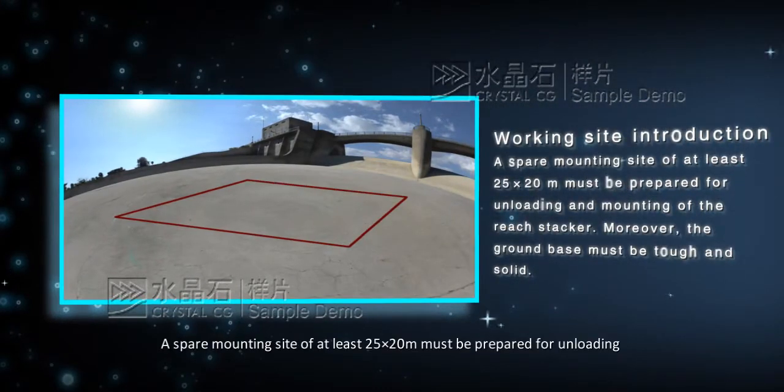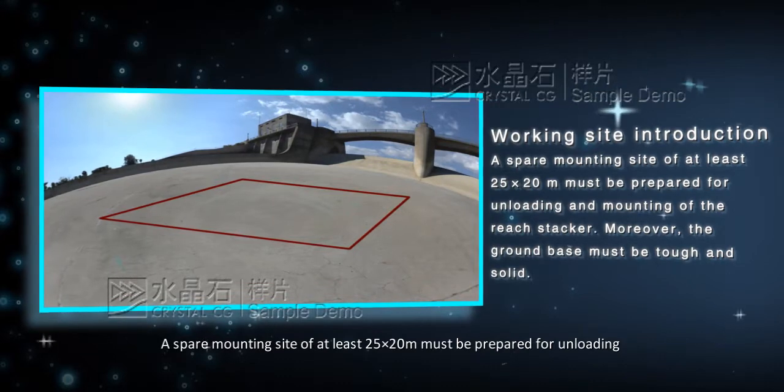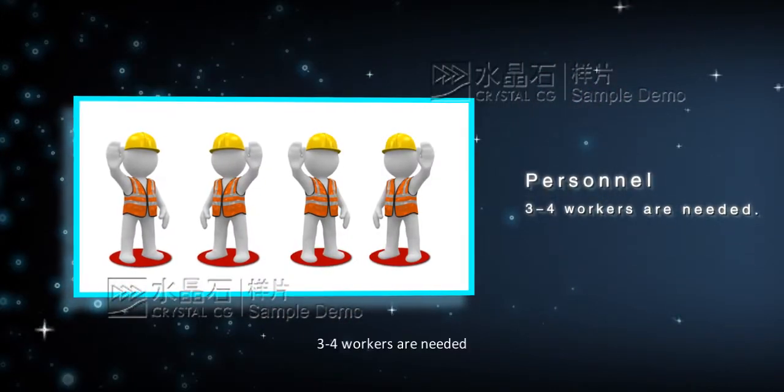A spare mounting site of at least 25 multiply 20 meters must be prepared for unloading and mounting of the Reachstacker. Moreover, the ground base must be tough and solid. 3 to 4 workers are needed.